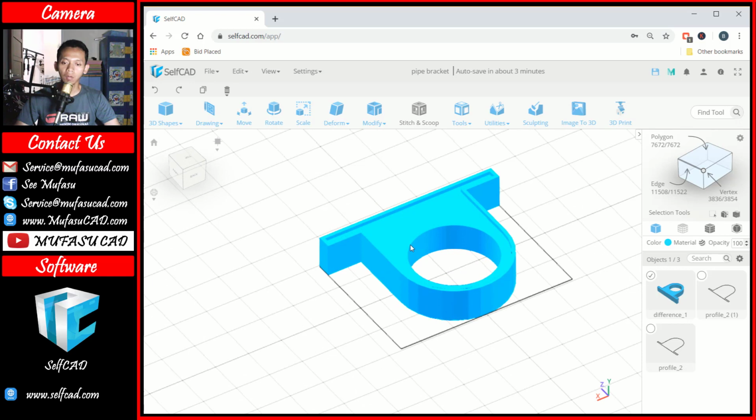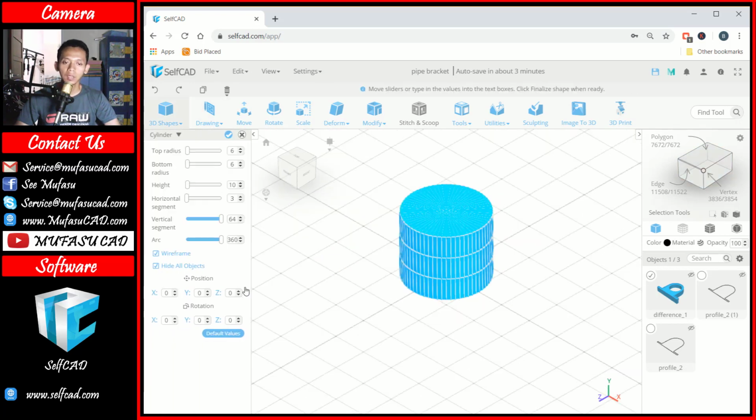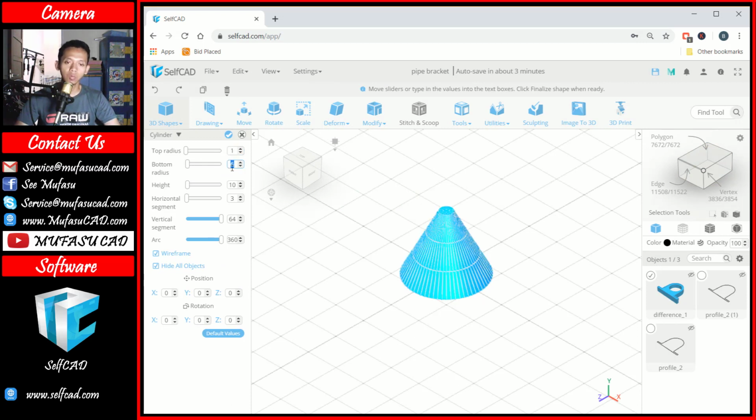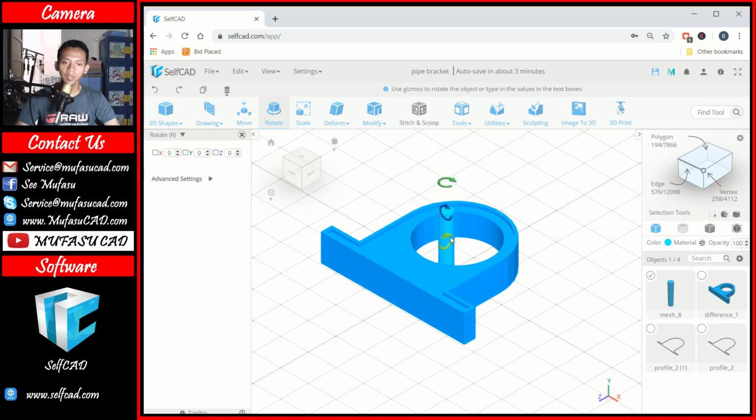So I will create another hole at this point. We can create a new cylinder object. For top radius, I will set into 1 and bottom radius 1. You can click OK to apply. I will rotate this object in the right axis. Okay, in the right axis in here, X, I will rotate 90 degrees. Okay, and next you can close.